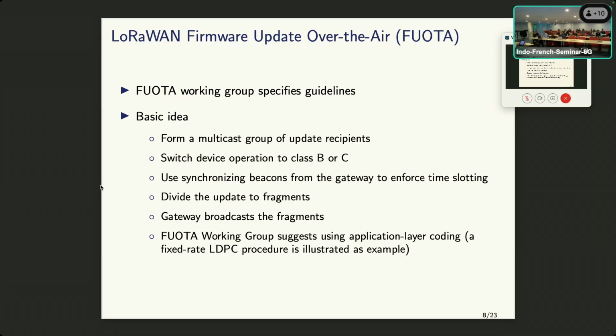And of course, because we have synchronizing beacons, we can incorporate some time slotting. The general LoRaWAN does not have the concept of time slotting, but during the FUOTA process, we can do that. Then the firmware update is divided into fragments. Each fragment is put in a LoRaWAN packet, or a link layer frame, so to speak, and those frames are broadcast. The working group suggests using application layer coding to correct for frame erasures.